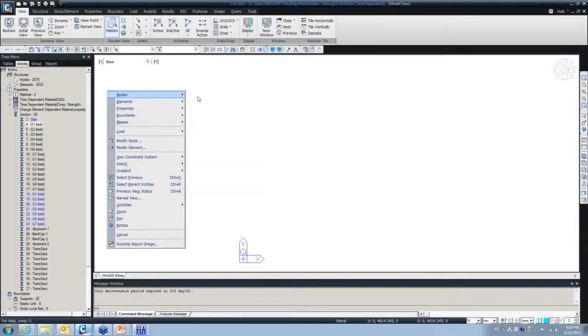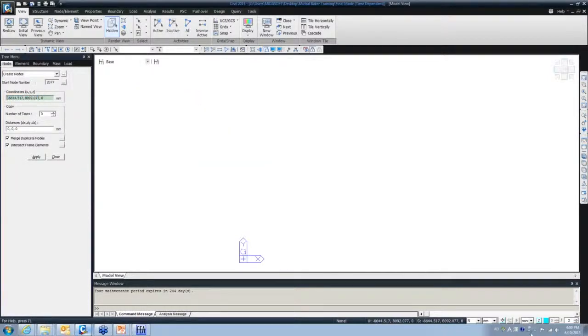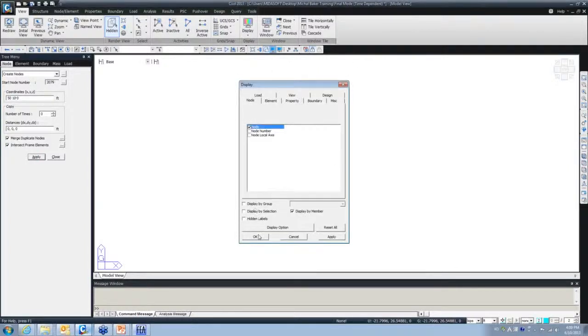And if I have, like, 3 nodes, let me just create some nodes. So I go to the nodes and create nodes. Let's say the first node, I want to put it on the feet. So the first node will be 0, 0, 0, apply. The second one will be, for example, 100 and 0 and 0, and the other one would be, let's say, 50 and 10 and 0. So I just wanted to create some nodes. Let me turn on the nodes so you can see them.